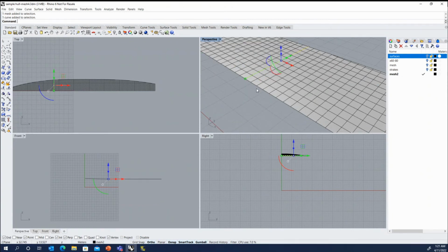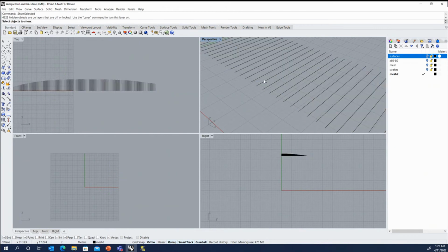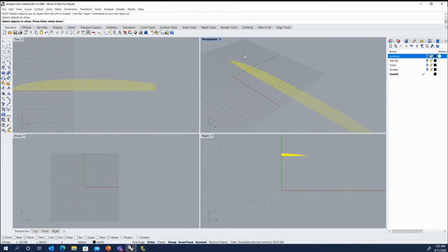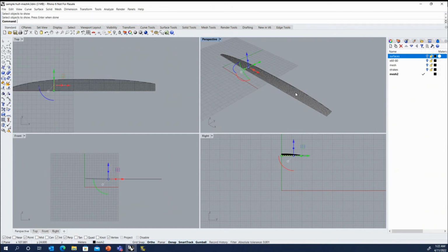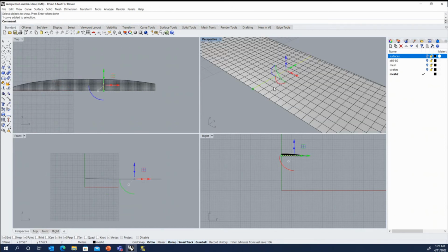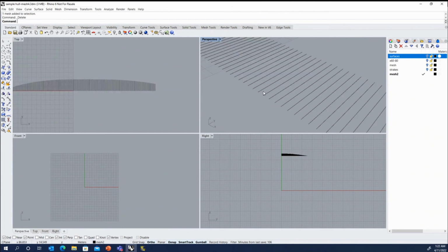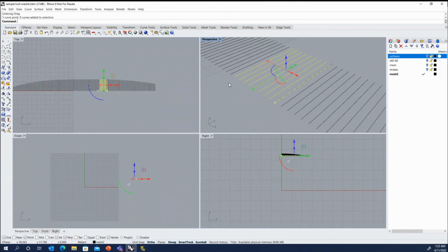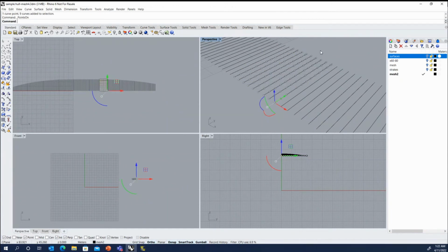It didn't destroy the original curves, it hid them. It put them in a group and then it hid them. So if you ever needed them back, you can do show selected and your curves are still there in a group. And these are the original single line curves. And then the new curves, if we were to delete this mesh, all of these new curves are polylines. If we turn on the points, you can see you have a node at each corresponding node in the mesh.